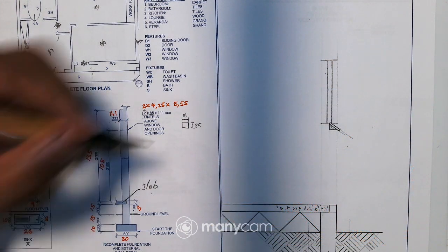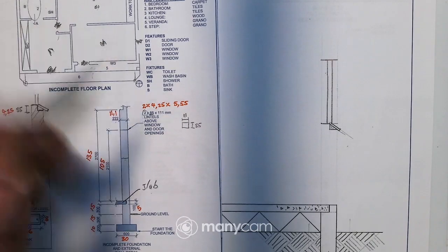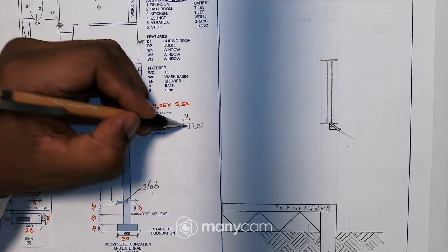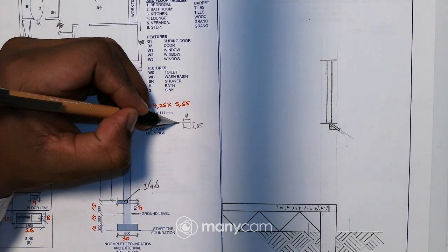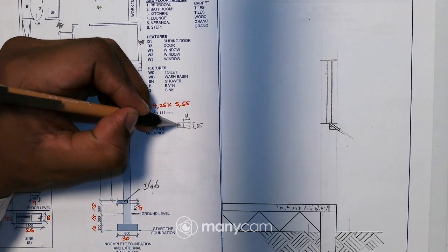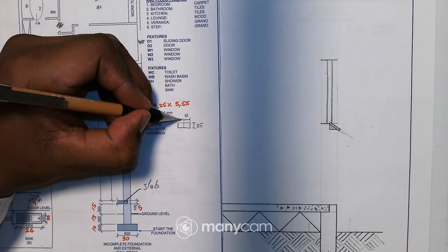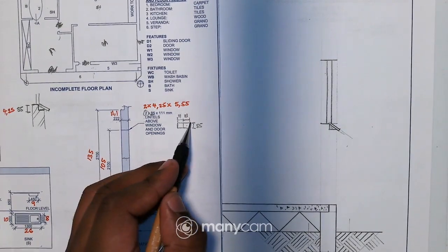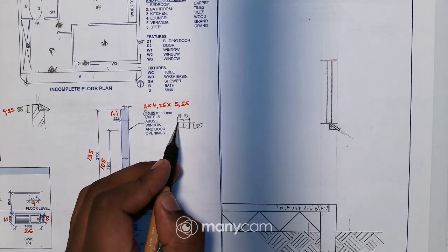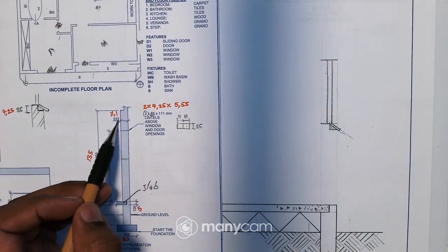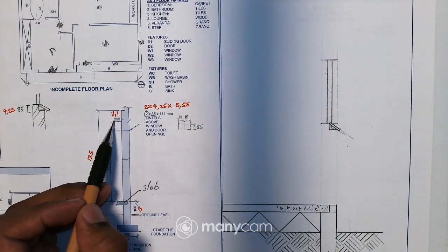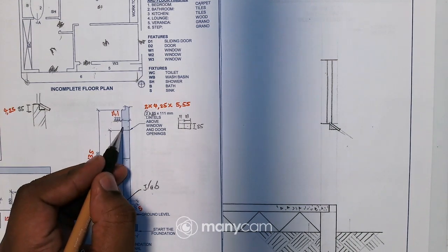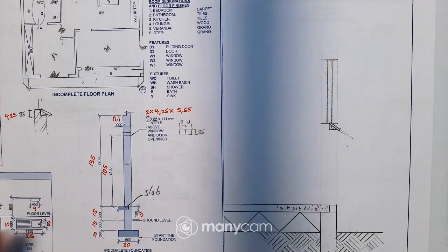Okay, so obviously I have the height there and the width, and we have to draw two lintels, right? That means this is one. That means the other one will be placed next to this one. So if I have two lintels, that means now the whole distance there will be 222. And if you check, the thickness of the wall is 222. So obviously the two lintels will fit there. So we'll place the lintels just above the window, right?